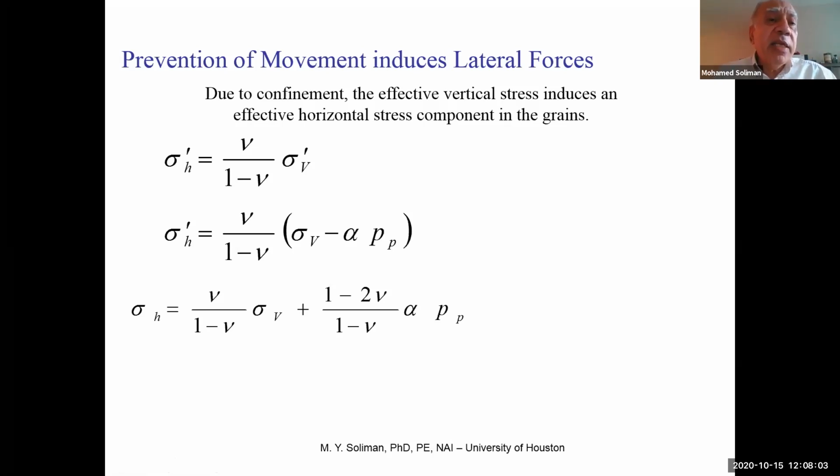Okay. In case of shale, if it's softer shale, it may be 0.4, a little higher than 0.4, not much higher. Sandstone maybe even less than 0.35, maybe 0.3. So you can see that this is the reason that the softer shale will have higher horizontal stress than hard rock, sandstone.